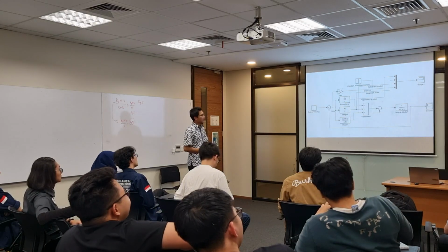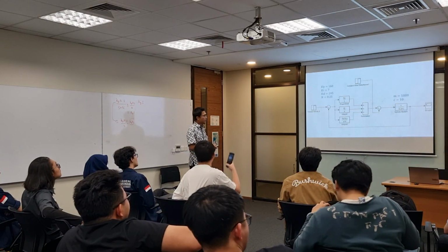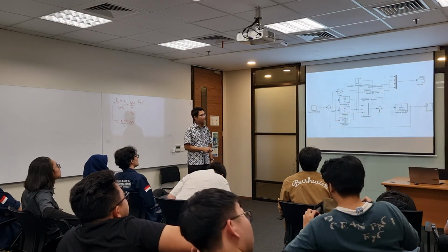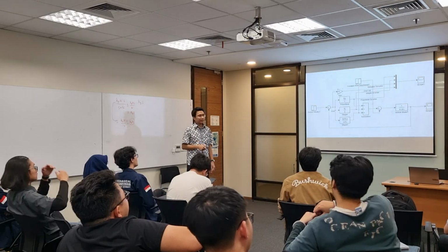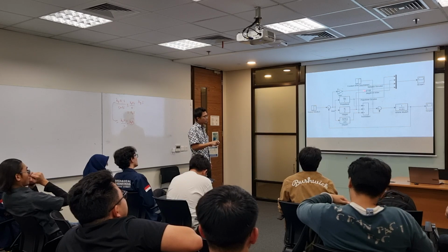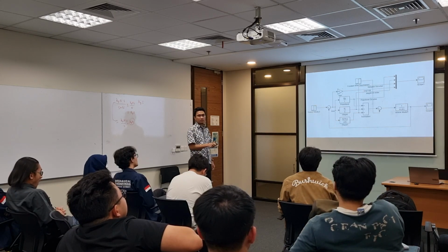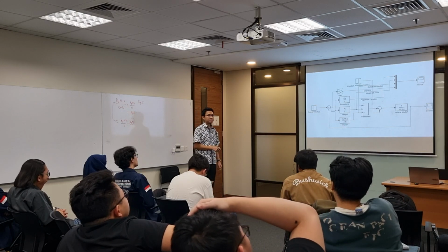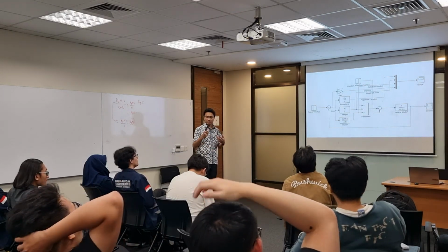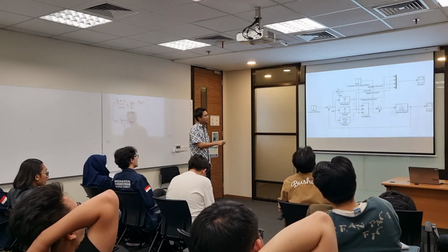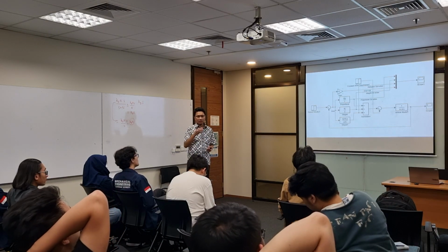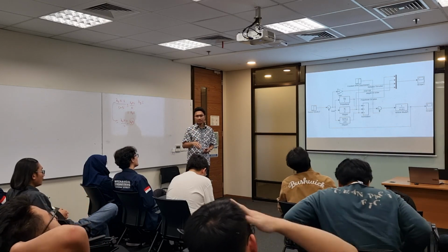The difference that I have from here is that I am plotting the control action. The good thing from simulating is that I can take out the signal from proportional control, integral control, and then derivative control. This one should be derivative. And then I compare them in a scope. You get what I mean? And then in here, I also plot the error. So I want to see how does the control action respond to the error.